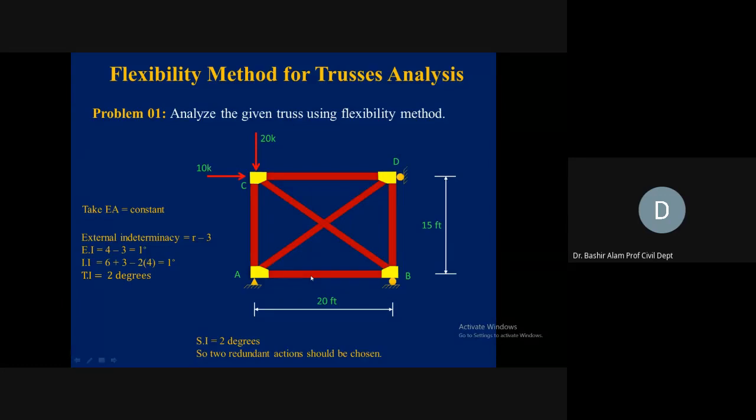Now cutting a member, if you see, you can cut AD. If we remove this member AD, we still have a very nice triangular arrangement of the members. Let's say AD is removed, so we have the ACB triangle, and then we have the C, B, and D triangle.